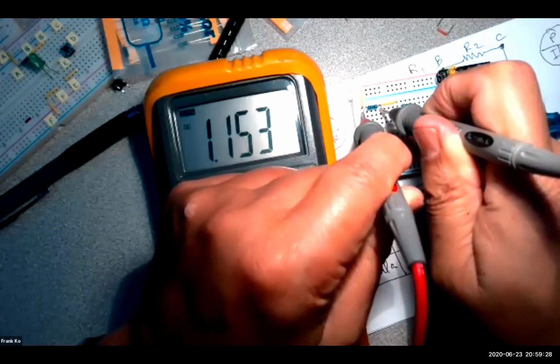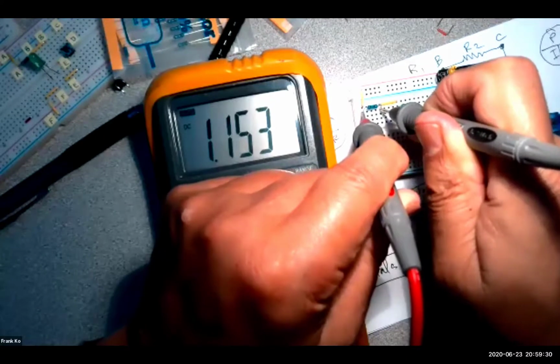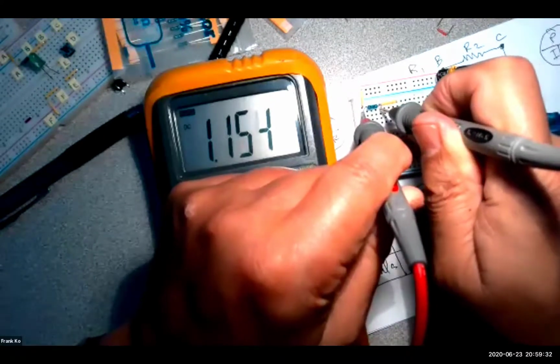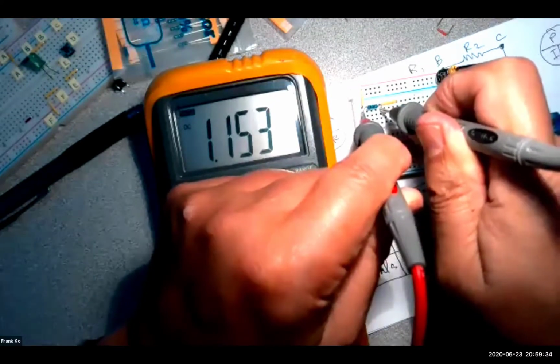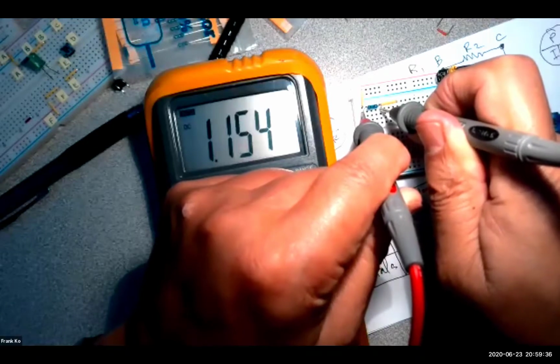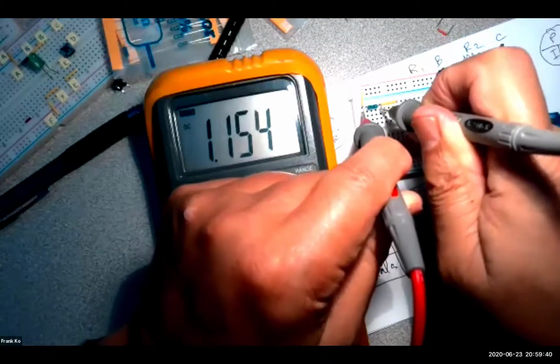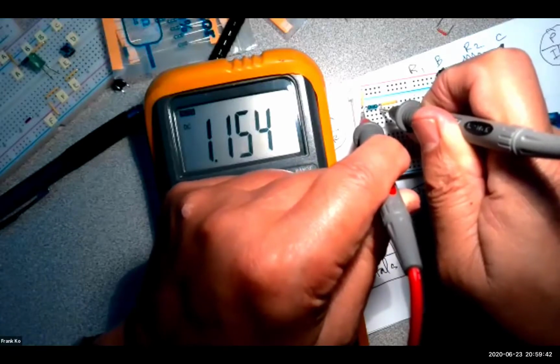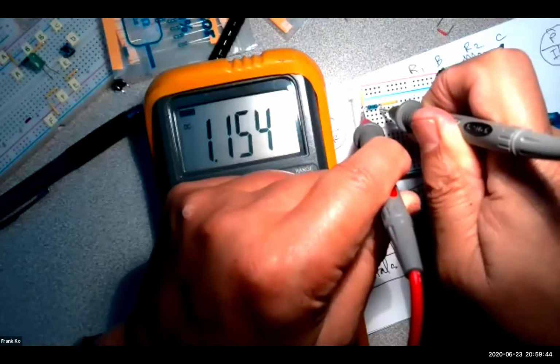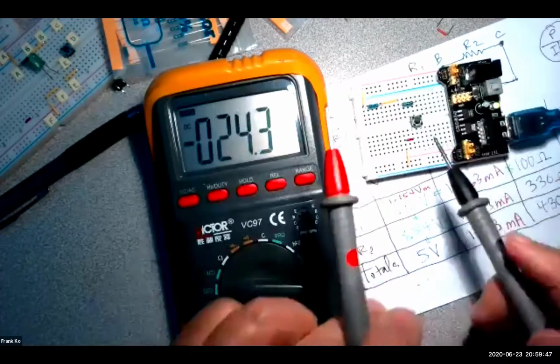And the reason why there's a slight fluctuation is because even with the stabbing technique, I'm pushing down fairly hard where the resistor goes into the board, because the amount of pressure slightly varies between my two hands. This last digit is fluctuating slightly. And that's because I'm using the stabbing technique.